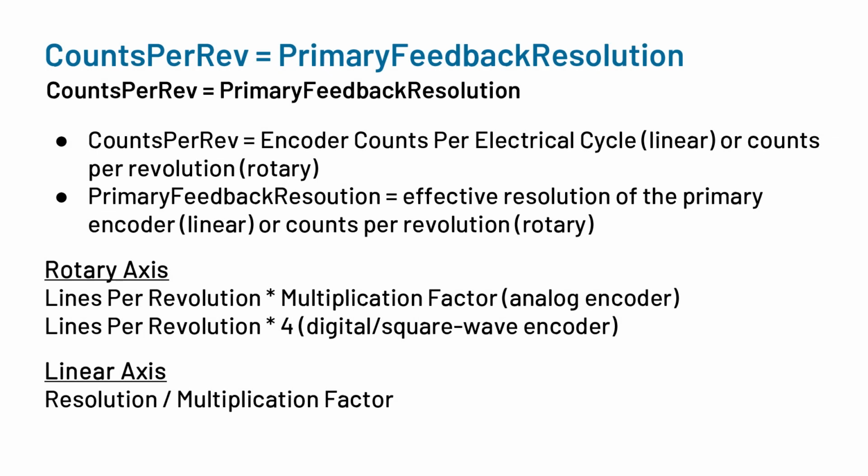To give you an idea of what manually reconfigured the parameters through option number 1 will look like, however, let's look at something like the counts per revolution parameter from A3200. This is a crucial parameter that dictates how many encoder pulses the drive should be seeing per revolution or per electrical cycle of a motor. This was renamed to the primary feedback resolution parameter in Automation 1.